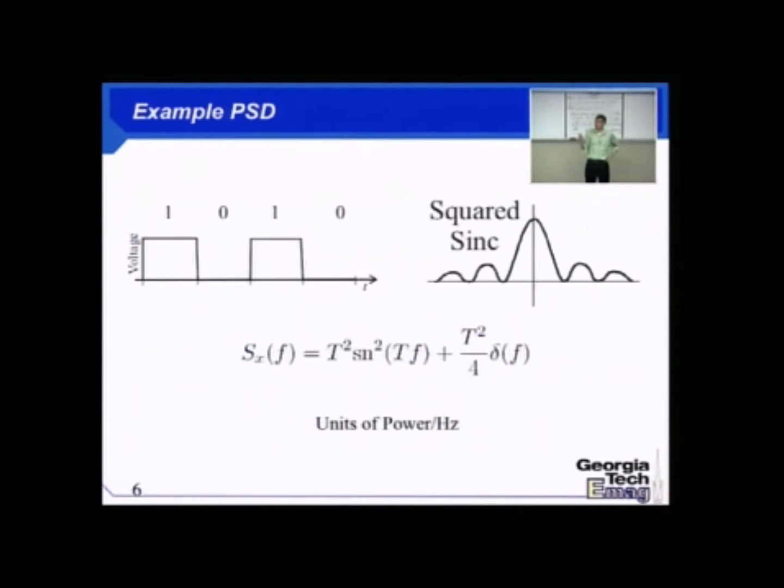pulses that are going to fit within a certain symbol period. You can see here I have 4 symbol periods sketched out, and all of my pulses, my square wave, fit nicely in that symbol period. And I can try to smooth things over, make triangles or maybe little bell curves or things that reduce the frequency content and keep me from rippling.